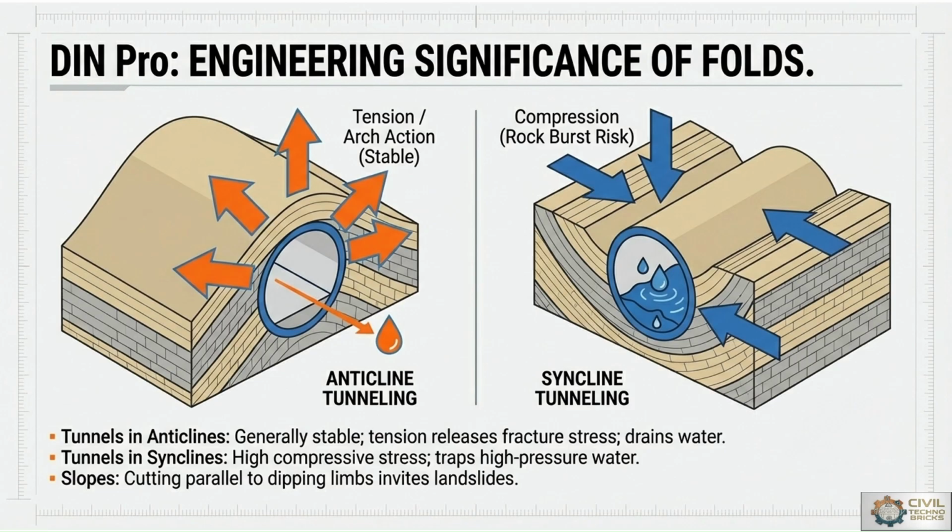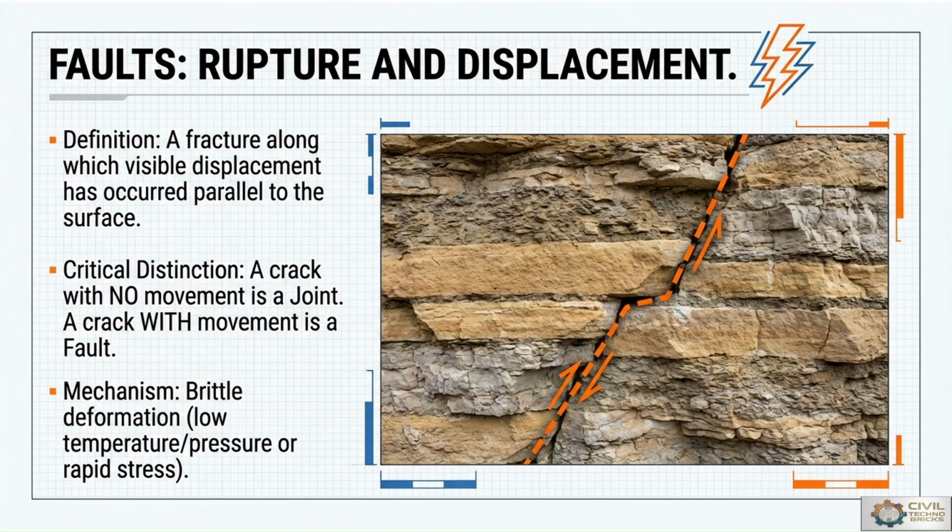So what is the importance of slope in anticline tunneling or syncline tunneling? Cutting parallel to dipping limbs invites landslides. The rupture and displacement, or we can say the deformation due to external forces, is the surface along which the rock displacement occurs.